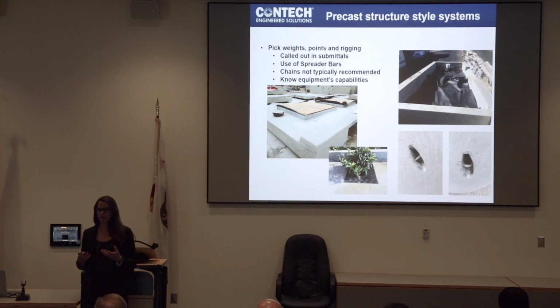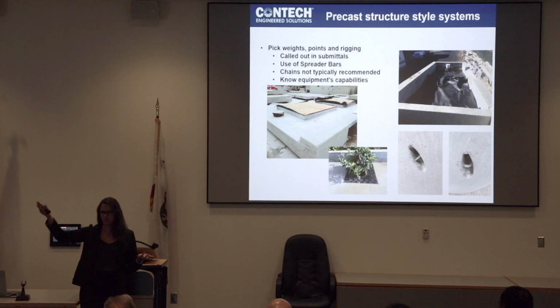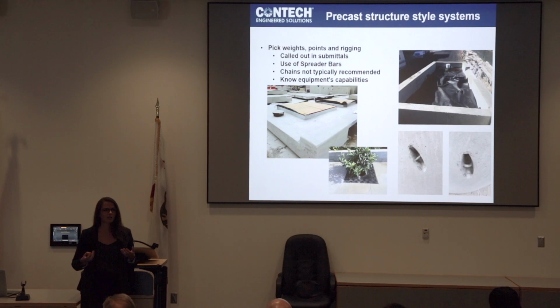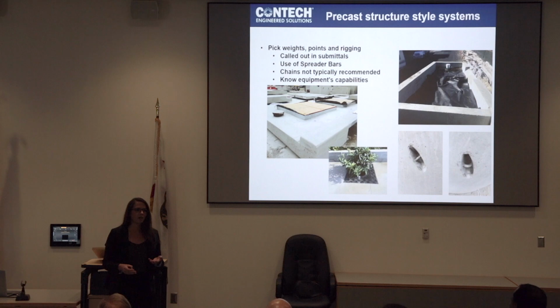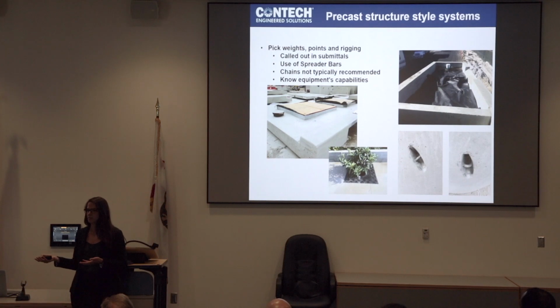When you are shipped a precast system, it is generally on a truck that's about 4 feet tall. When you imagine those picks, they're, say, 3 feet above that. And then your sling or spreader bar, whatever you're using to pick up this system, let's say is no less than 10 feet. You're already at 17 feet height restriction with those calculations. And as you raise that arm, you can pick up less weight. So take a typical CAT 330. When you meet those criteria, you just brought the lifting capability of this machine from 25,000 pounds down to 13,000 pounds.